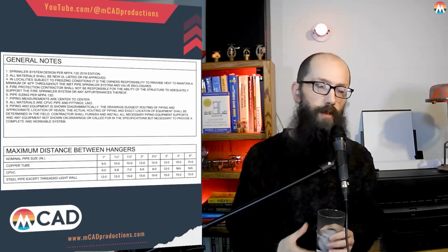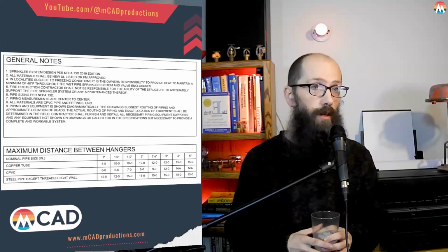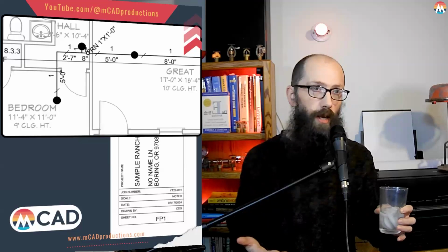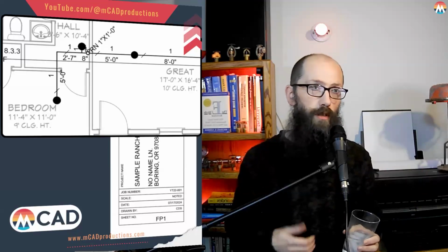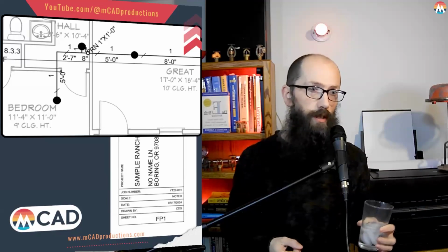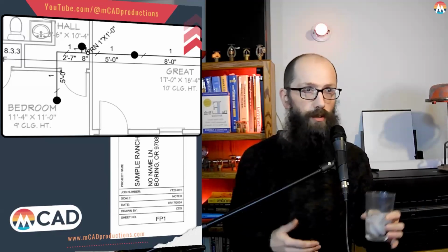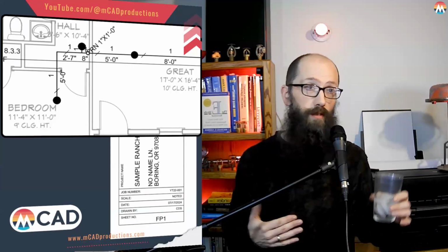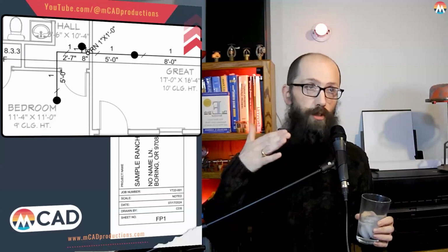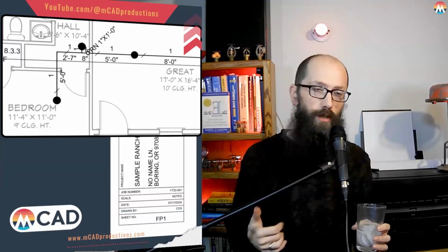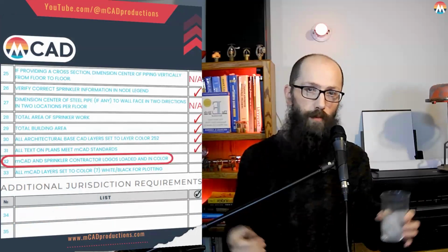There's only specific places where they are used, and there's reasons for them. Like we have with the dimension style, the text on the title block with the address, you can see all of those are the same size text. Even the dimensions from the drawing are the same as the text on the rest of your drawing, and it matches, same font, everything.